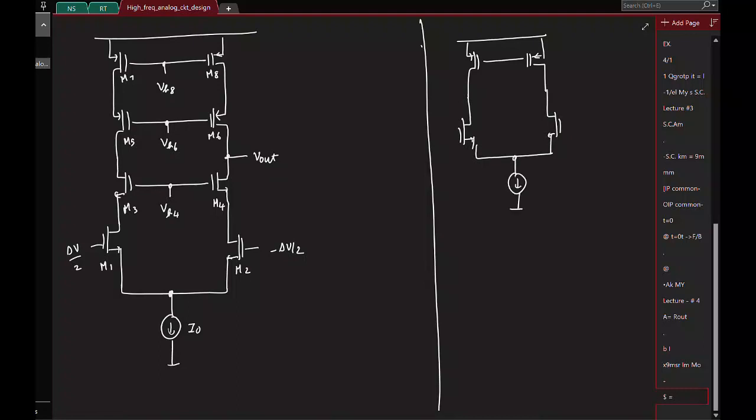right? And if you think about it, the way we derived the final circuit was, we said we'll try to obtain this bias voltage for the PMOS transistor, and we wanted it biased at such a voltage where the current flowing through the PMOS transistor is what? I0 by 2, right? And of course, initially we started with some separate branch and merged it in the same network. And that's what resulted in this diode connection, right?